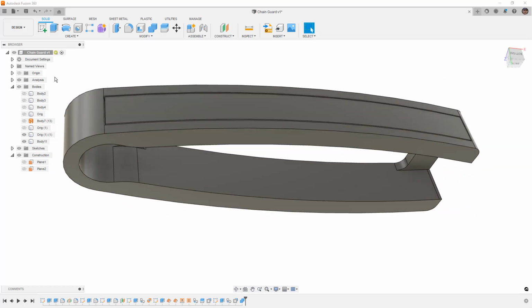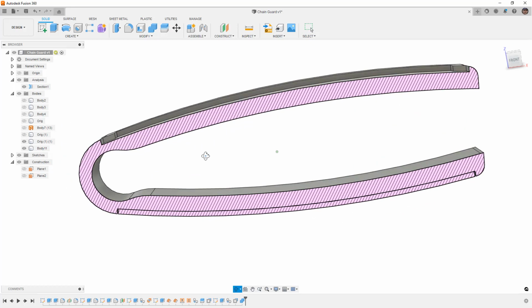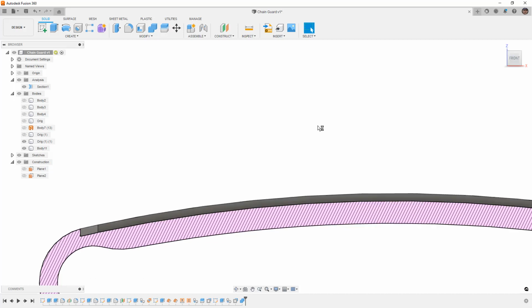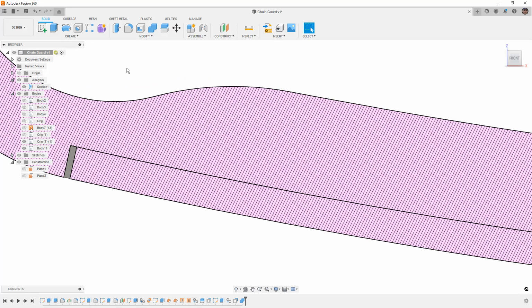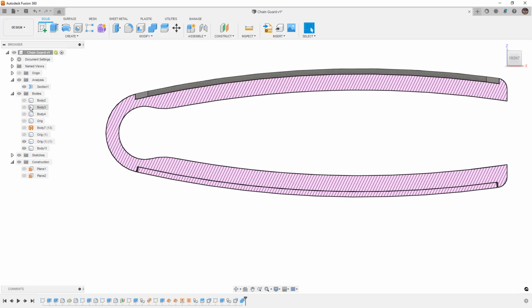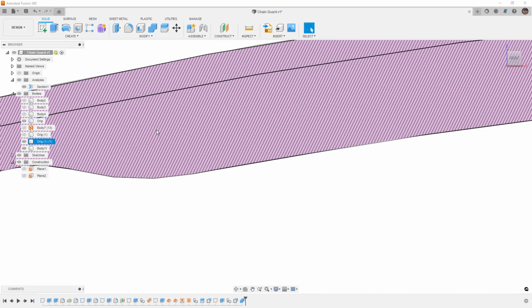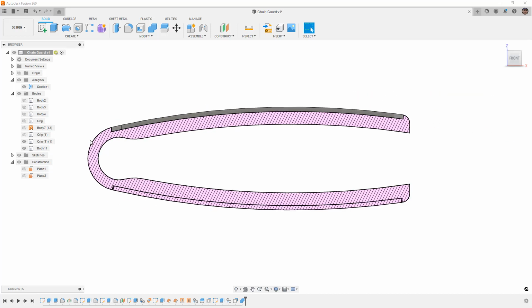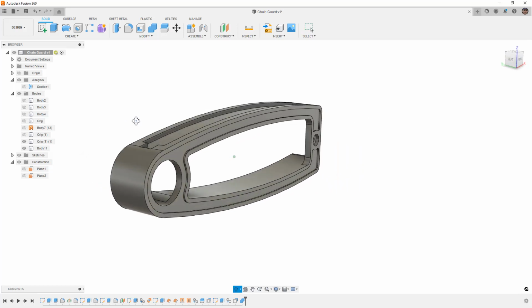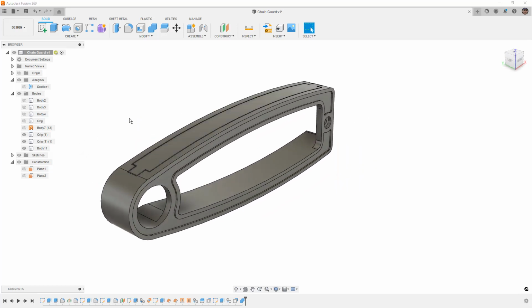And once again, if we take a look at a section analysis, go ahead and turn this on. You can see here, double click the mouse wheel, that we've got something that matches the inside shape, again, because we did a section, we offset, we did an extrude cut, and then we shrunk it down. So it really is going to match that geometry. On the top side, you might find that the piece here might not match perfectly if we start to do some surfacing tools where we allow it some leniency in how it extends and knits things together. Most of the time it'll be okay, but in some cases it's not going to be okay. So those are a handful of ways that we can achieve the same or very similar results.